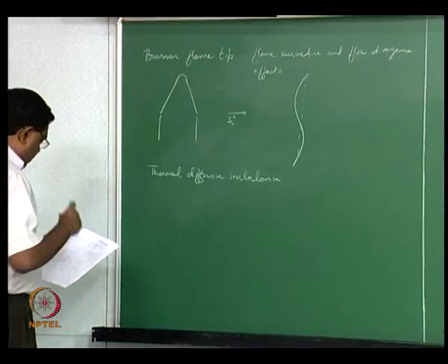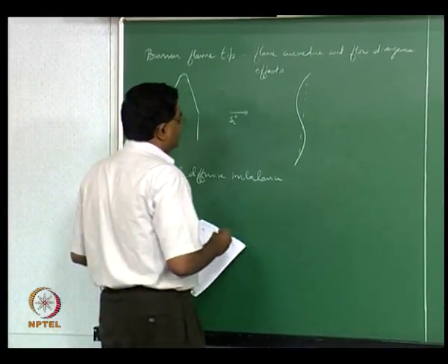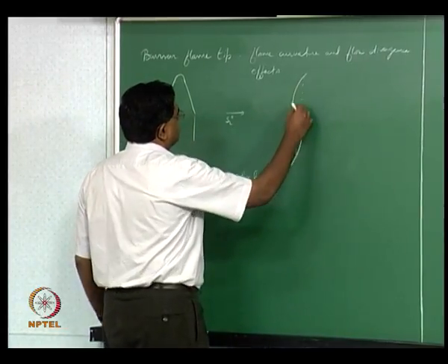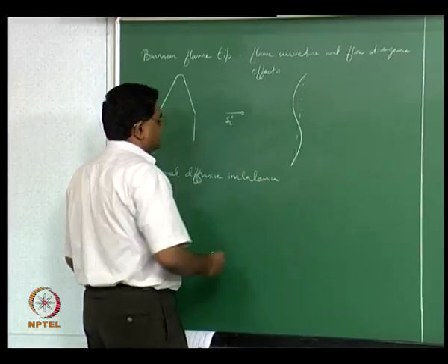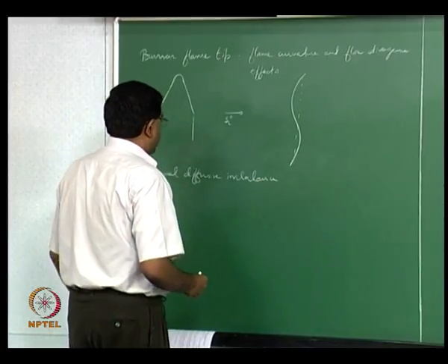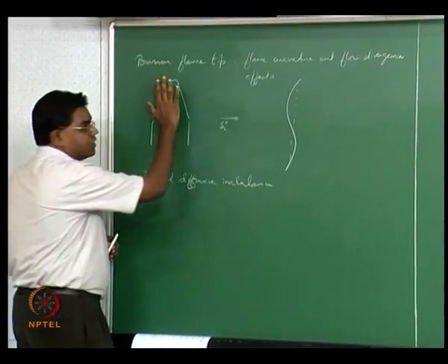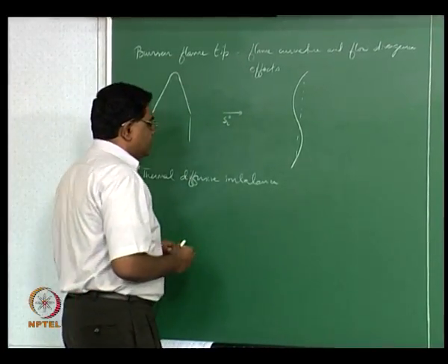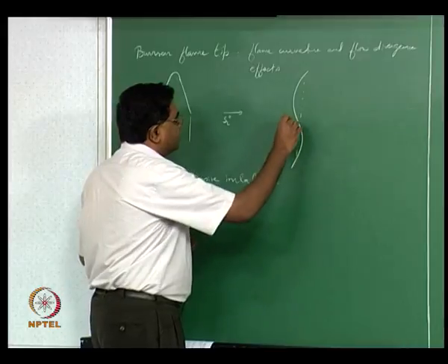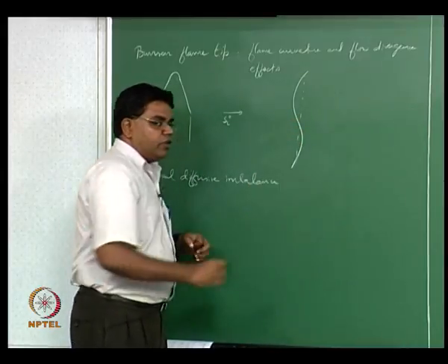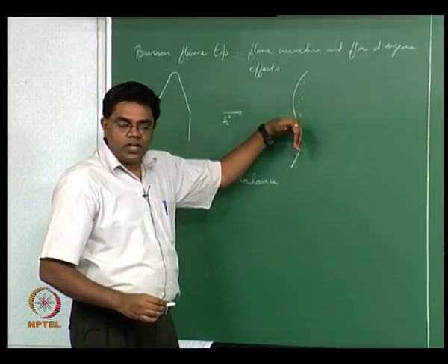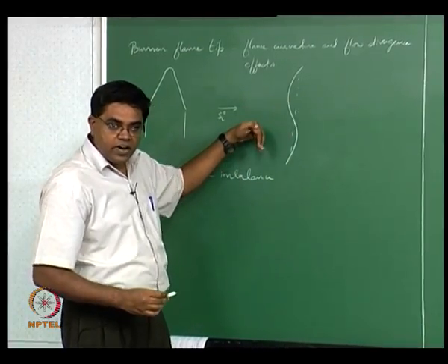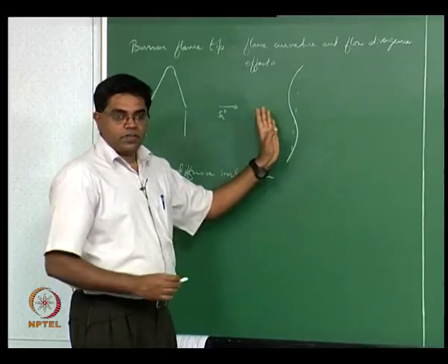So when you have a flame that is curved, let's take the concave part. This is a little bit more intuitive, and it's also what's happening in the Bunsen flame tip, so this is pretty instructive. You're now thinking about a curvature that is of the order of, not exactly equal to, but still a little greater than the flame thickness.